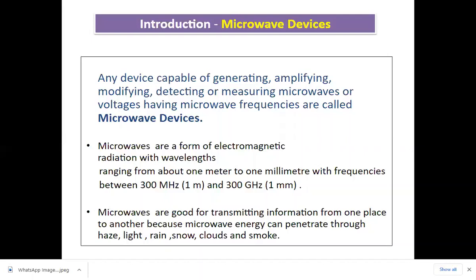Basically, microwave devices are used for the purpose of generation of the signal as well as to amplify the signal. Before the inventions in microwave semiconductor techniques, it was the vacuum tube devices working for the same type of applications. But the conventional vacuum tubes like triodes, tetrodes and pentodes are less useful signal sources at frequencies above 300 MHz. They were not handy. The power consumption is very high. There are many reasons why conventional tubes cannot be used for microwave or high frequency.